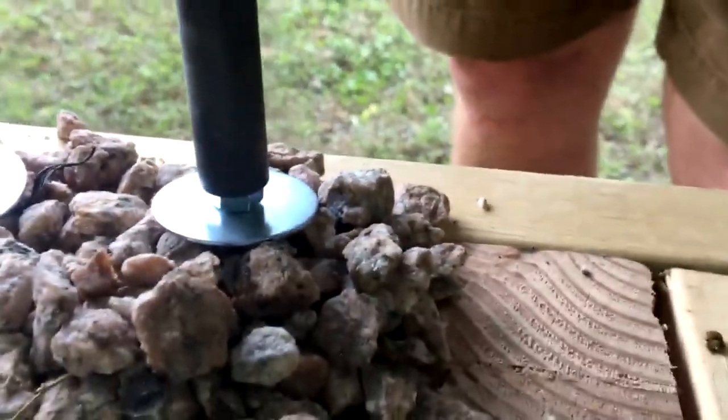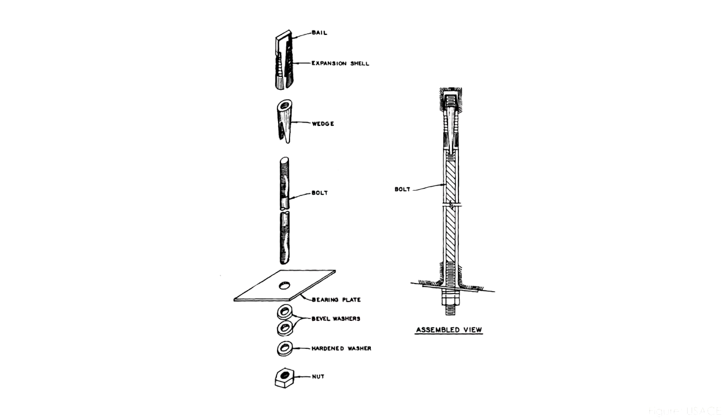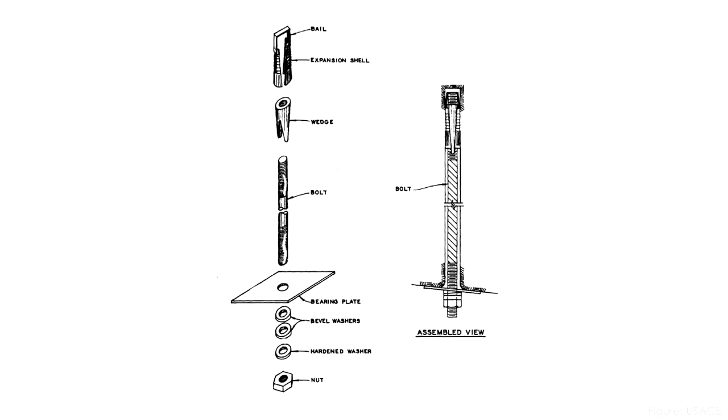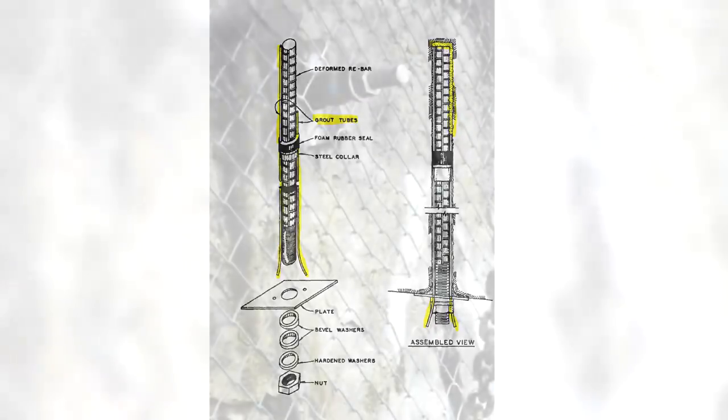Another obvious difference between my demo and the real world is that we don't normally have access to the top of the bolts to add nuts and washers. Instead, the rock bolts are secured at their ends by some other method. Two of the most common methods of anchoring are a wedge device and pumping in grout. It's very similar to putting an anchor in concrete or even hanging a picture frame in drywall.